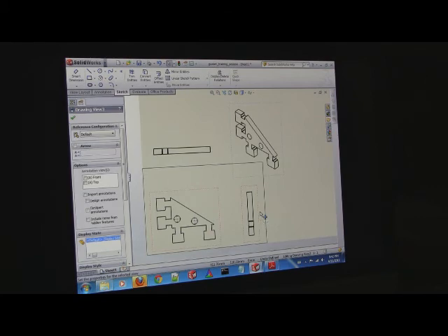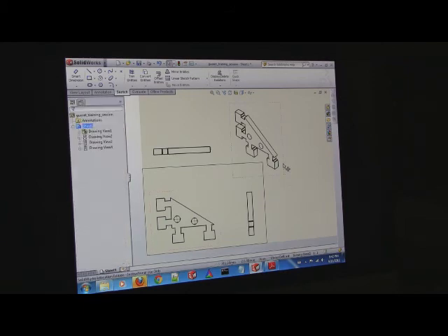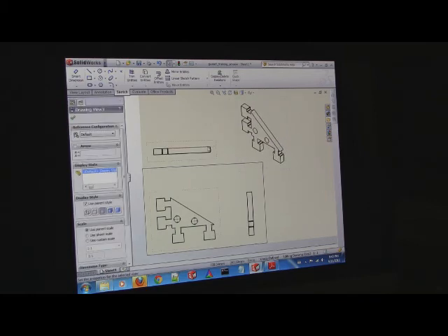How do you get them moving across? How do you move them? Oh, yeah. It's kind of irritating in SolidWorks. You cannot just click on it. You see how the box appears? Usually if you click on the outside of the box, it'll let you move. Okay, does everyone have these 3 orthographic views? Or 2 orthographic, 1 isometric?